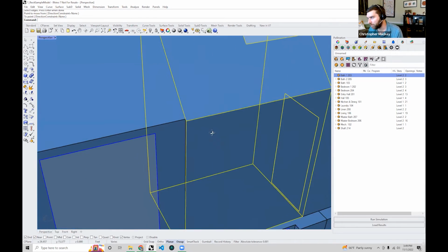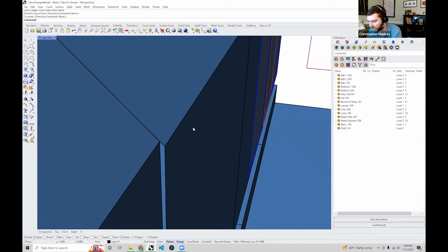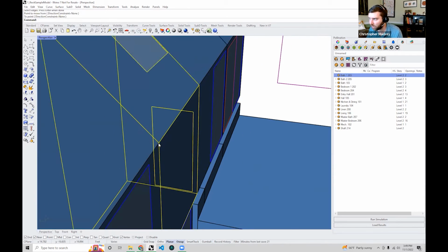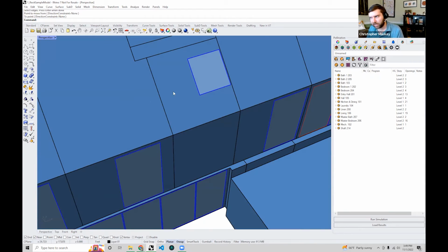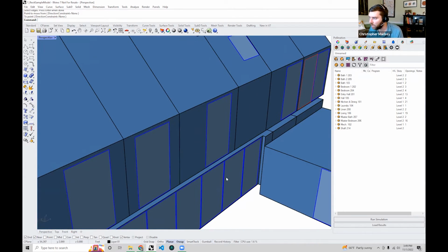And of course, we also had this on this side, because the whole room was extruded incorrectly. We can do the move edge command again. Let me type move edge. I can select this little edge here, hit enter, and then just snap between the endpoints to make sure that's all good here. Okay, all right, so that'll solve that issue. Next time we solve adjacency, that'll be perfectly touching. I won't get this little extra sliver out on the edge here, so that'll be nice and clean.